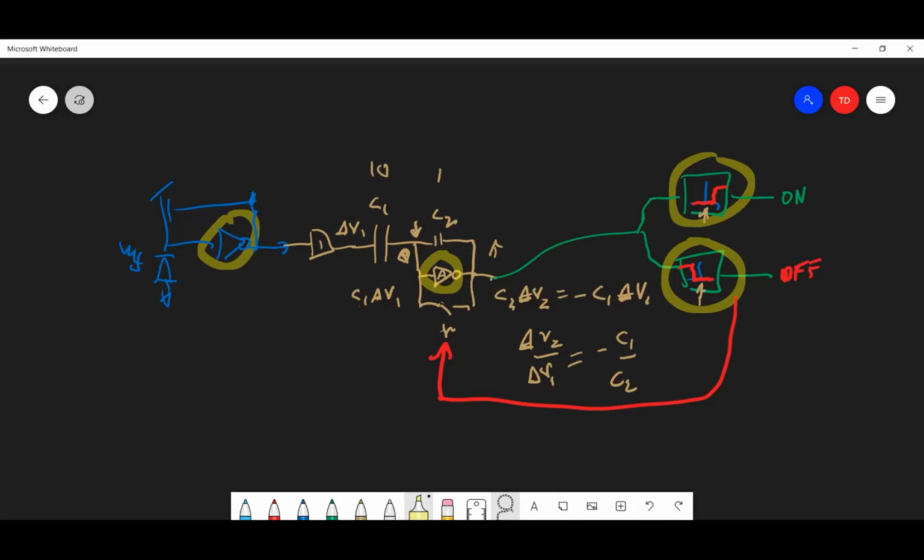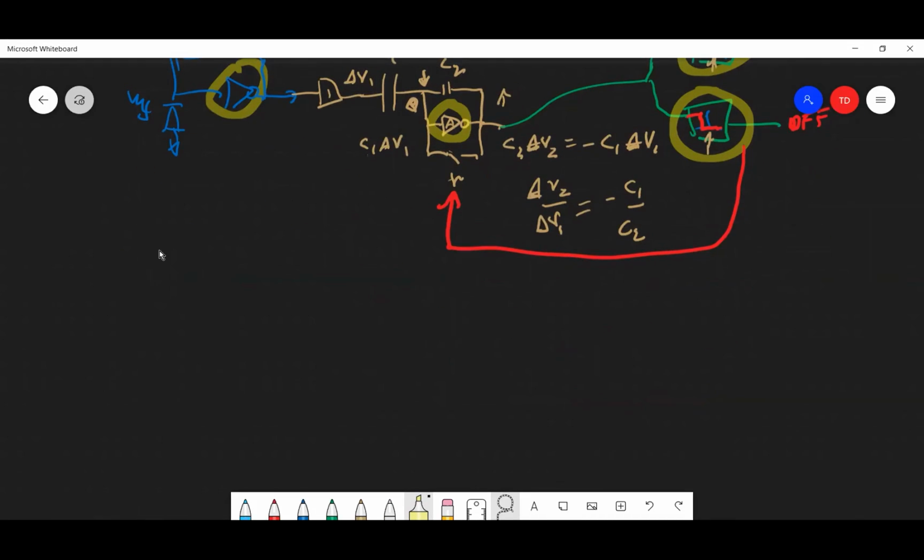Isn't it the same we use for the transimpedance amplifier? It's just an inverting amplifier. They're all just 2 transistor inverting amplifiers. Yeah. So I'll show you the complete circuit, and it's a beautiful, simple circuit. I'll just draw it for you here, maybe in this color. So here is the input capacitor. Then you have a bias current down here. That's an N FET. A P FET here. Then you have another bias current here. Another P FET. One more bias current. One more P FET.